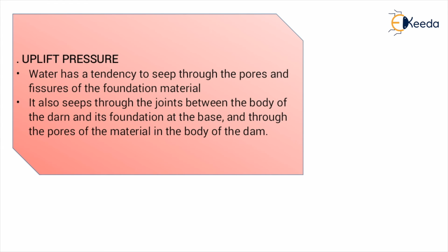And if there is a gallery in the body of the dam, then the uplift pressure will be gamma in bracket H dash plus one third of H minus H dash. This is according to the USBR recommendation.